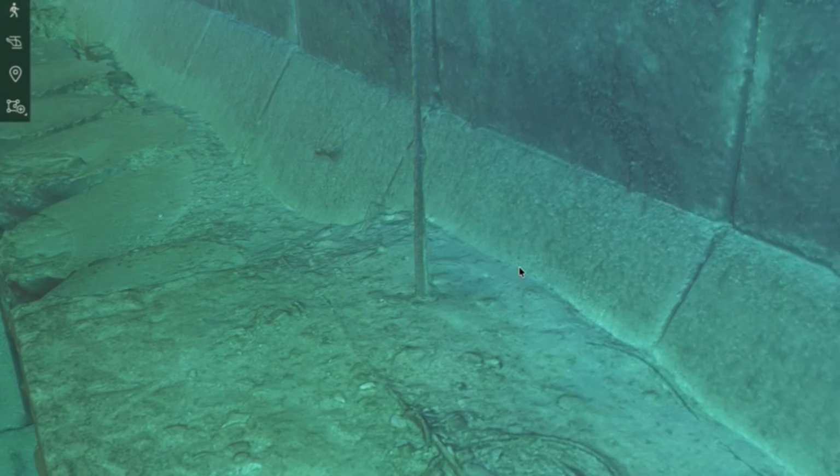But from my perspective, it is just the boat or a vessel that has pitch and roll understanding, and it measures the speed of sound, and it also measures everything. So the results can be really great, and it's usable in high turbidity waters, which are in most cases above 50 NTU. The visibility at a turbidity of 50 NTU is around 1 meter. So if you have particles and you go to the structure, you will see it from 1 meter.